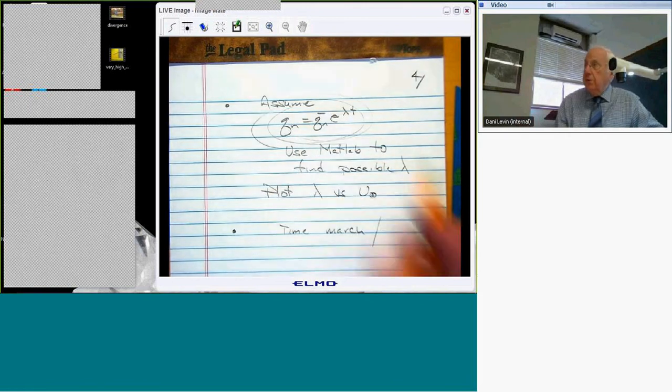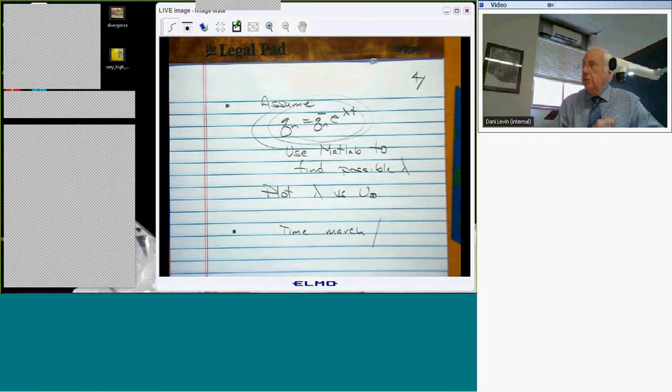You could set some initial conditions, let it march in time for a given u infinity, and see if the solution grows or decays. That's not what flutter engineers normally do, but in this case that would be possible. And you might even want to do that just to check that the two methods give you the same answer.